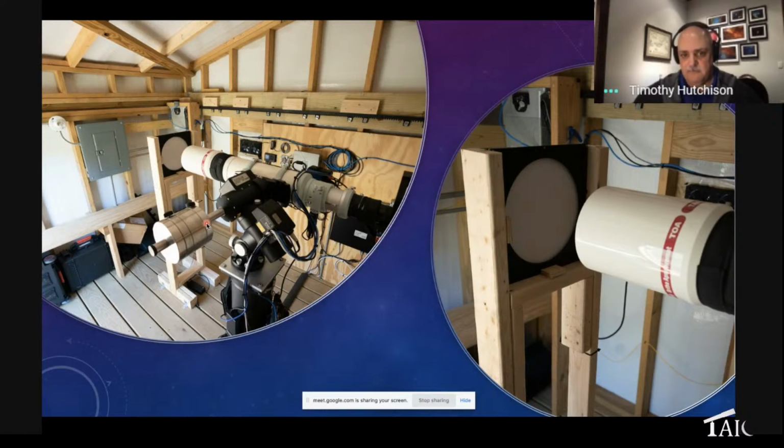Yeah, I work with a facility that's got about 25 roll-off sheds, and everybody's got a little bit different philosophy as to just how high their pier should be and where their scope should be. And that ranges from pretty much what Tim just described, to making sure that you put that pier low enough, and the walls are all pretty much a fixed height anyway, but you put the pier low enough so that no matter what happens, you can always roll the roof closed.